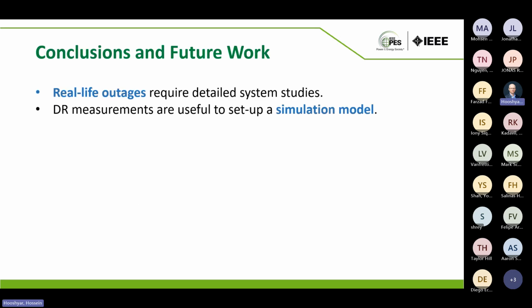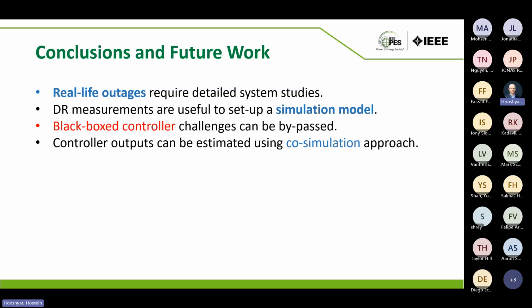To conclude and put the future work in perspective: for real life outages, this analysis is always required by system operators after any outage, for root cause analysis and for preventive measures to avoid such incidents. We typically have good-resolution disturbance records at most critical units, so getting the data for these simulation setups is not a big challenge. But the main issue is that as we replace synchronous machines with more and more inverters, the black box control problem grows, with even less transparency in the models, especially when nonlinearity needs to be handled. So this is an alternative approach: rather than guessing and fitting a certain model to make the waveforms fit, we replace the unknown part, optimize the output of those controllers, and then back-calculate what the controller structure should have been.